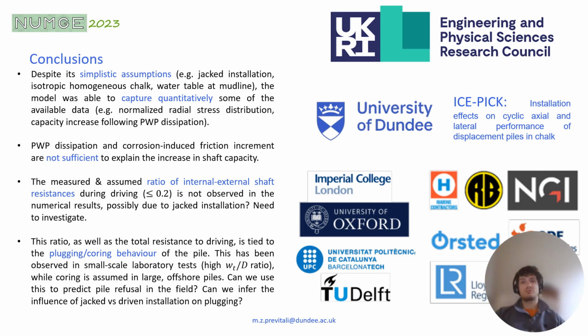The measured and assumed ratio of internal shaft resistances are very different from those reported in the literature, and this could be due to the fact that we carried out jacked installation, while typically in literature people do, at least for larger scale piles, driven installation.